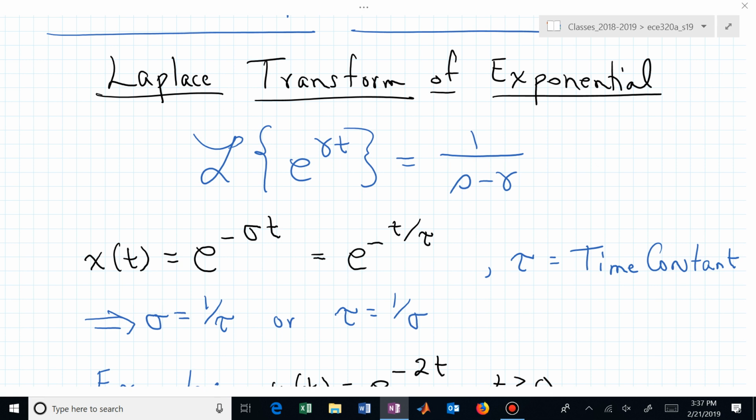So now if we had a time constant of 1/2, if little t, if we've now progressed one time constant into that exponential waveform, we now have e to the minus 1/2 over 1/2, or e to the minus 1. Do you remember what e to the minus 1 equals? 1 over e.